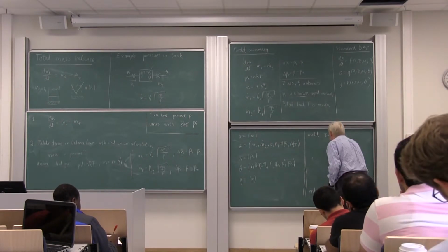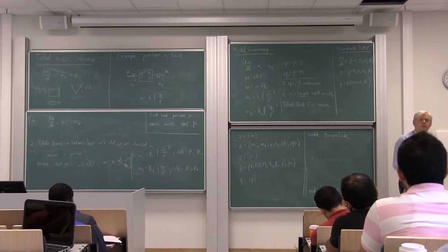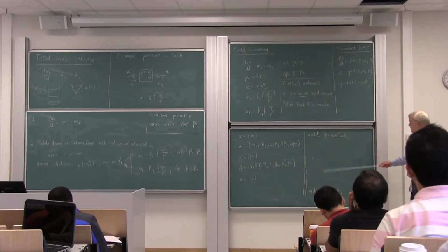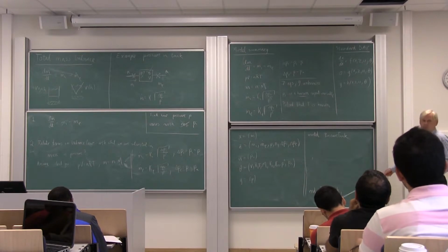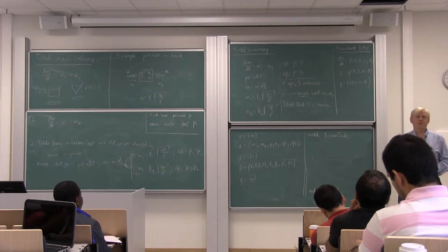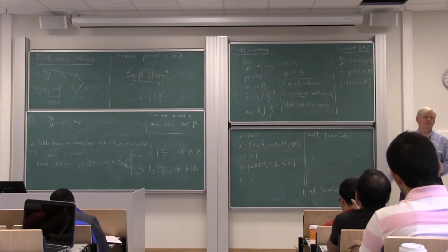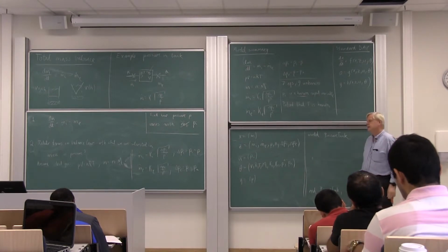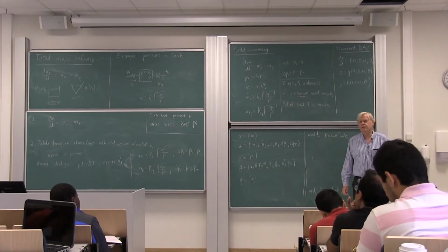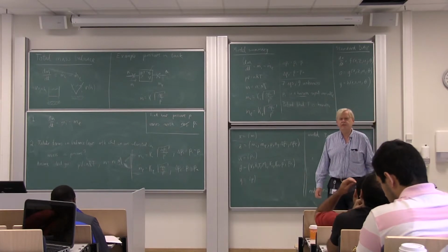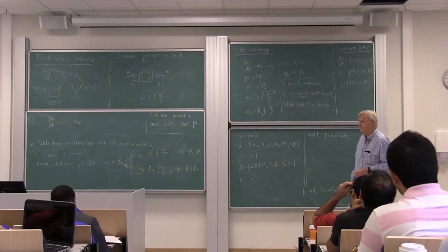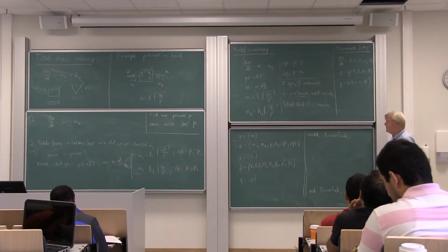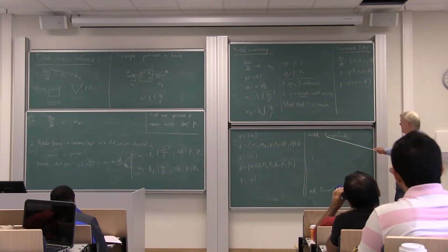And then semicolon. So this has to be the first line, and this the last line. You can call it whatever you want. You can call it my tank or whatever. And standard, that's one of the things I need to upgrade from in the lecture notes. The standard in Modelica, I didn't know that when I started, but the standard is that class names should start with a capital letter.